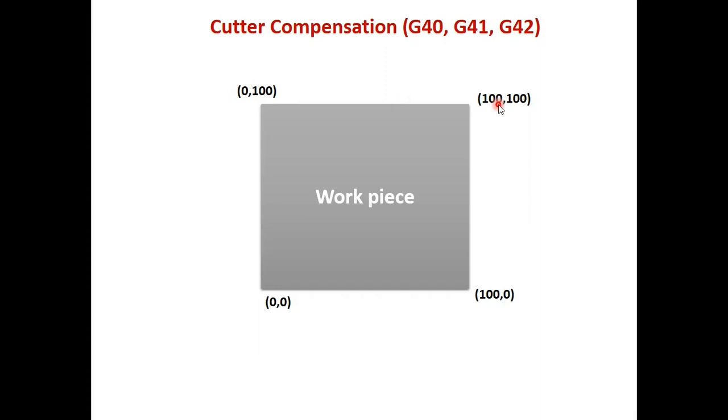Now let's say I got a drilling tool of, let's say, 10 millimeter dia. So this is the point at which the tool is standing, the blue color, so that is away from this one. And then I start doing the program. What happens if I give now here the center, if I don't give the tool compensation, and if I say move this tool to 0 comma 0 and start doing the machining like this straight, so you can see what will happen.